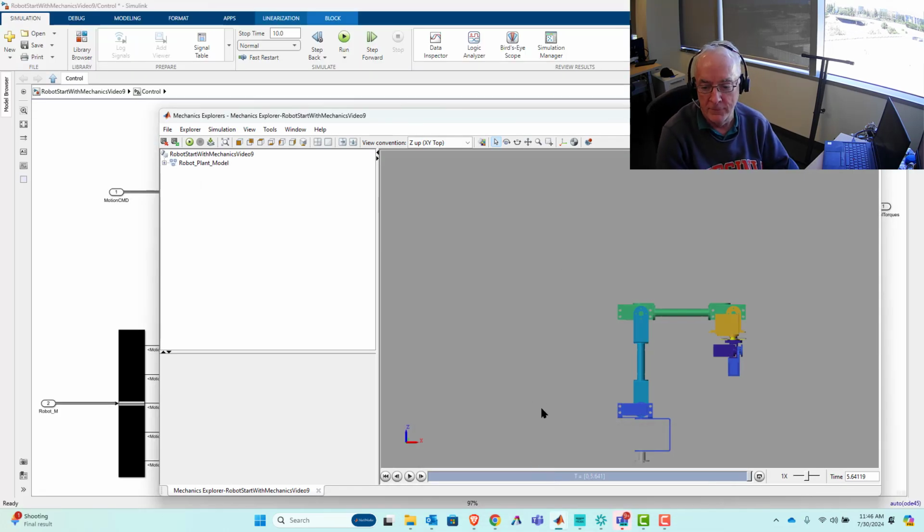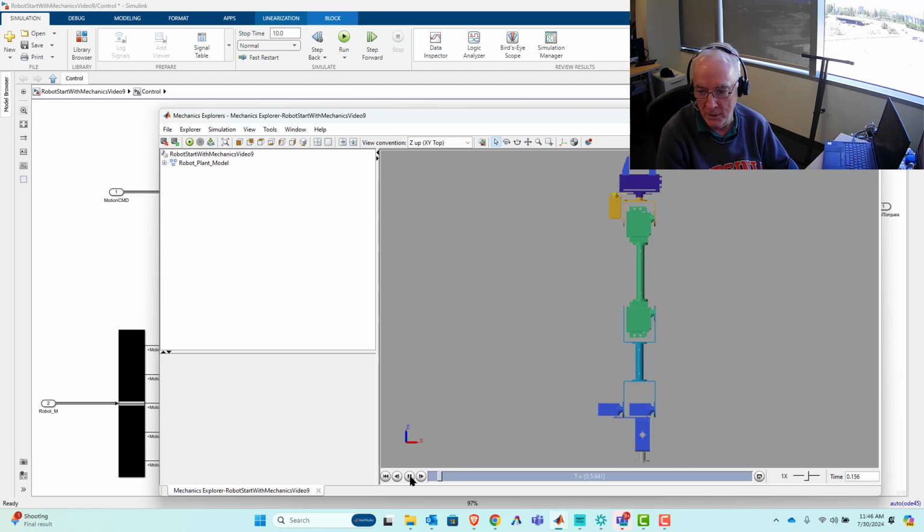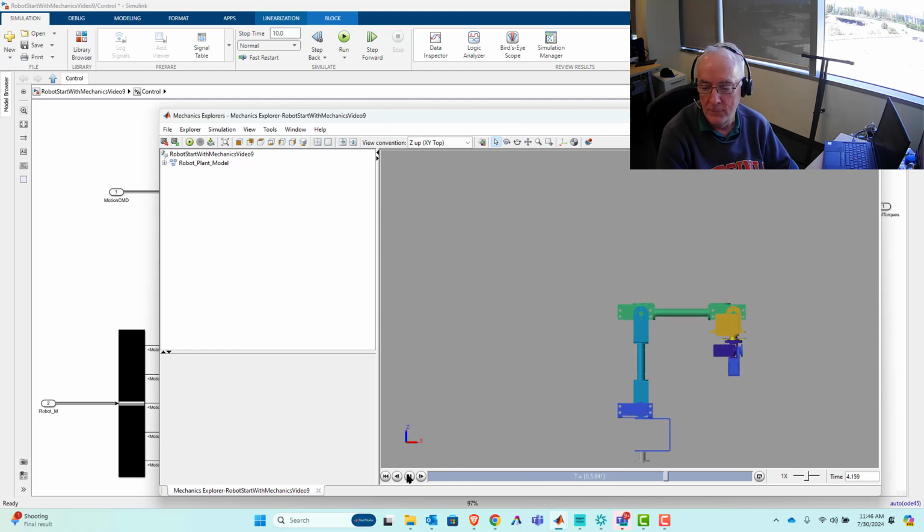Okay, so let it run for about, what is that, 5.5 seconds. So I'll just show in playback mode that for a sample time of 10 to the minus 5, it works beautifully. Again, if you think of how numerical integration works, hopefully it makes sense that if you're trying to figure out the area underneath the curve, the smaller you make the delta x or the delta t, of course, the better it will do.